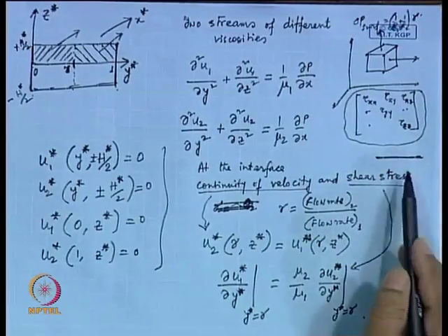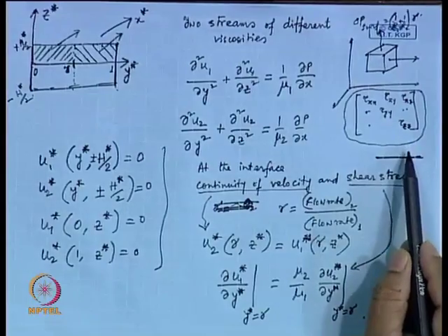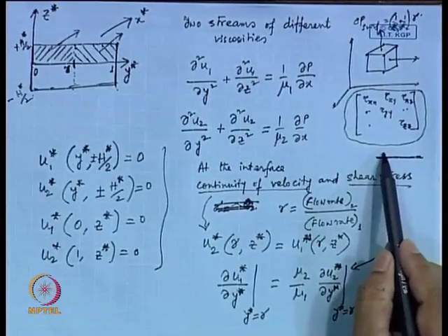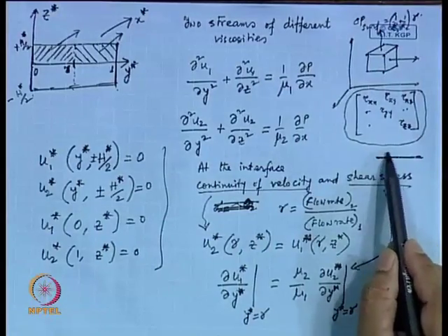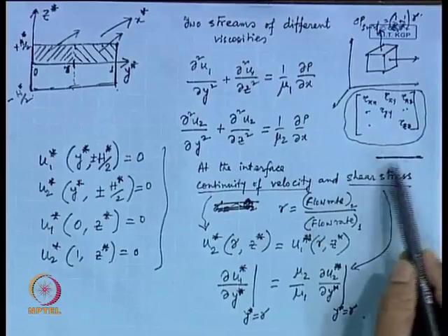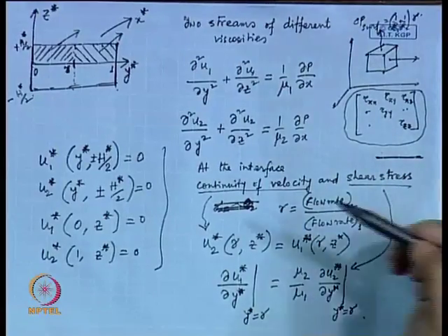That is one reason, and because of that the counter ions would be attracted to the surface, and there would be development of one particular ion near the wall. So, that would introduce some Coulomb force in this Navier-Stokes equation, that we will discuss in connection with electro-osmotic flow, but that is missing.